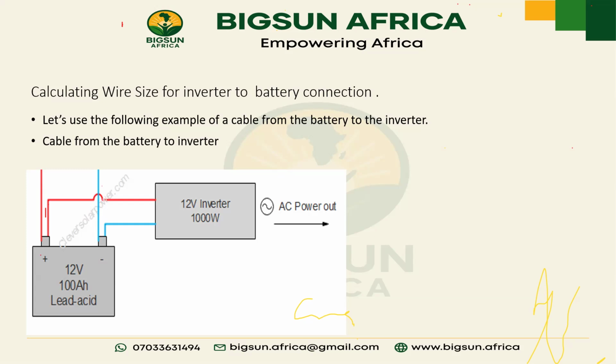It shouldn't be more than 3 meters. So try to reduce the distance between your cable and your inverter to maybe 1 meter. Let's just calculate it so you understand it, so it wouldn't be as if I'm the one that said it.